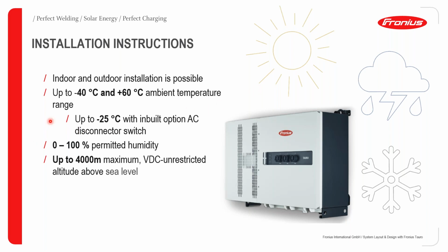And then in terms of temperature, we are talking about the inverter being able to operate from temperatures starting from minus 40 degrees to 60 degrees Celsius. And the plus 60 degrees Celsius is what will be relevant for the tropical areas, especially in sub-Saharan Africa, where in some areas you'd expect very high or abnormal ambient temperatures.